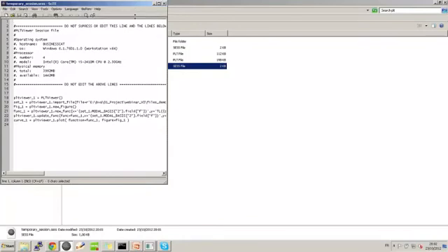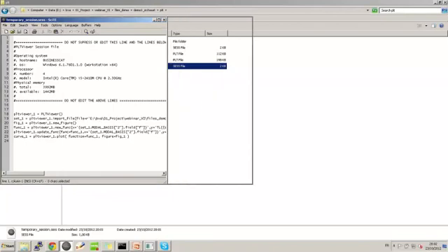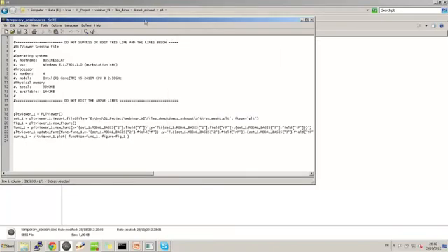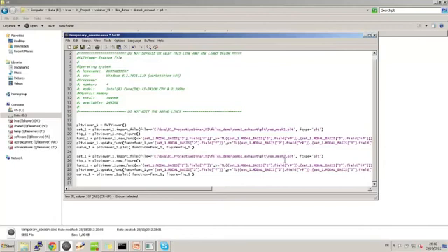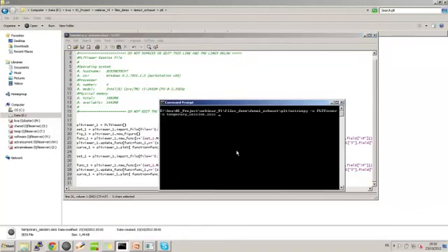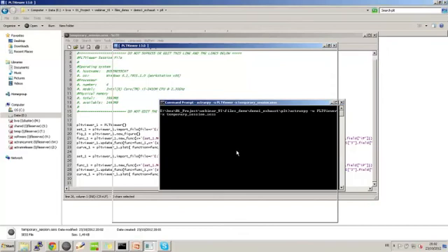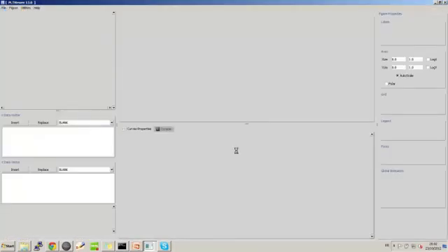So what I can do is just copy paste this whole part where we are importing the file and we are creating the curves. The only thing that I will do is change the name of my PLT file. So here I will write West Mesh 2. And in order to avoid having a new figure, I will just suppress this line over here. And now I'll launch here directly in the same folder the command line to launch the PLT viewer in batch mode. So if I execute this session, what I will get is the two produced curves on the same figure.